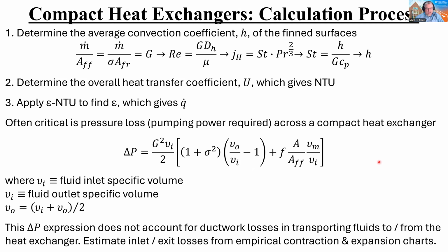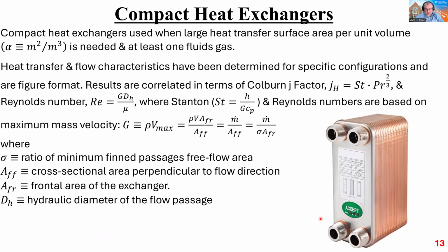Which is if you've got this tiny little heat exchanger, you guys know what's coming. You're going to get an enormous pressure loss across this heat exchanger. Sometimes that pressure loss can be so high that it requires pumping power high enough, right? Remember, again, everything in here is very thin, right? It's all very thin copper, very thin aluminum, right? We're trying to maximize heat transfer, so we want all of these thin little channels.